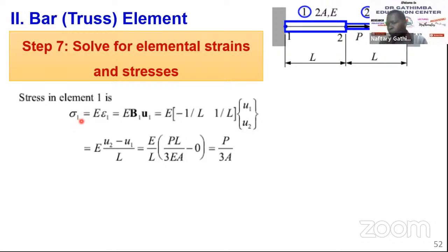So, Humphreys, from this expression, why I did not go the extra step? Remember, when you are solving equations, it's good for your practice. But when you are in class, for example in an exam, you only need to calculate what is required. So our equation here doesn't need the value of F. Directly using this equation, you only need to get the displacement, and of course the strain displacement matrix. I believe you can also get the force and use it to get the stress by using F over A. Try that and see whether you can use the other direct method that we have been using.